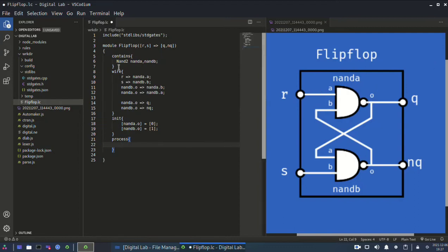If we generate it automatically, there is an issue. If you consider having another component before this gate, and you process this NAND A first, before processing the gate before that, it could cause an error. So to avoid that, we define the order so it is processed before that, and doing it manually I believe is the best method. This is also an alternate thing we have introduced in this language.